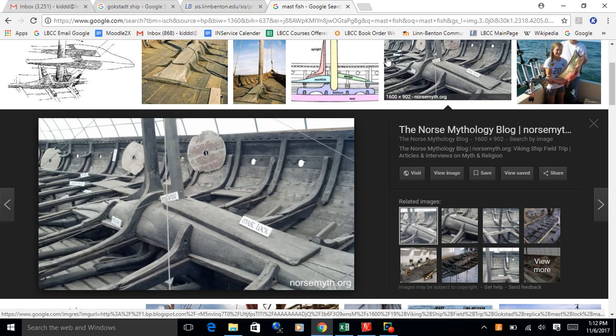Yeah, there's two ways I think you could do it. You could model it as a pin joint, kind of a roller, more of a, you call it ball and socket in 3D. Yeah, okay. And what that would do, that would model more stress up on the cables, on the stays that are holding it vertical. Or you can model it as a fixed connection, and then you'd have a moment here that you'd have to deal with on the mast itself. So there's different ways you can model this.